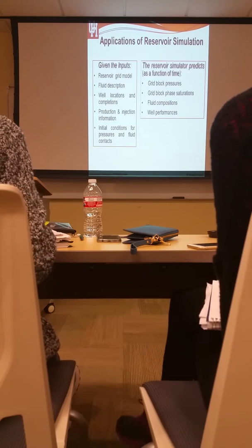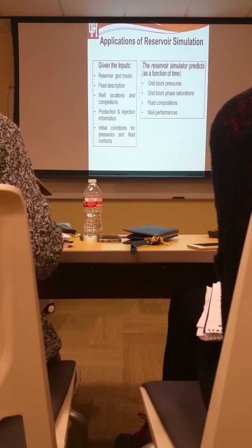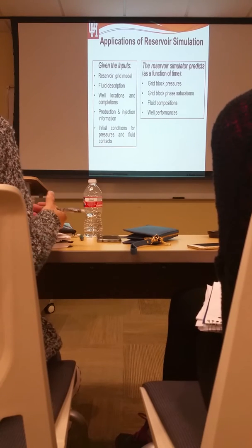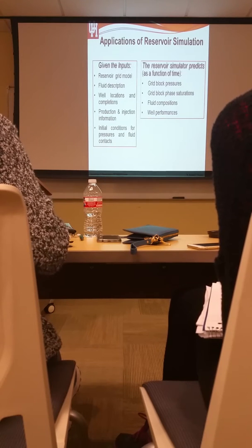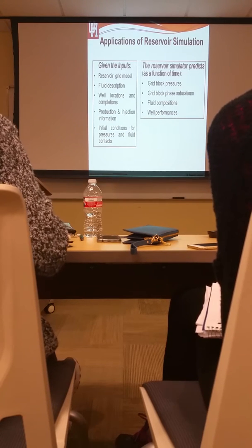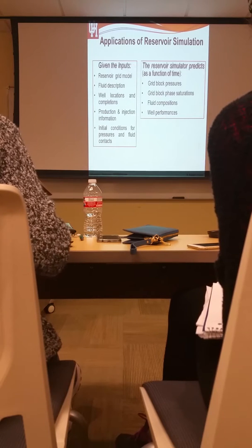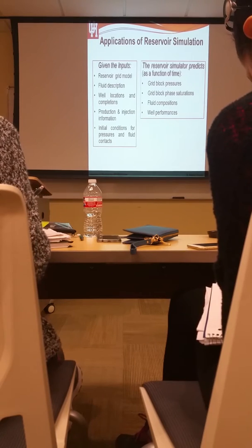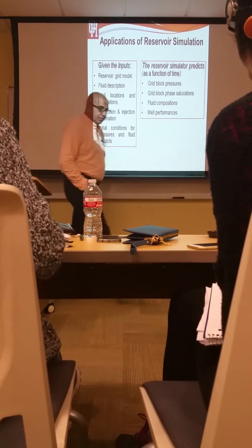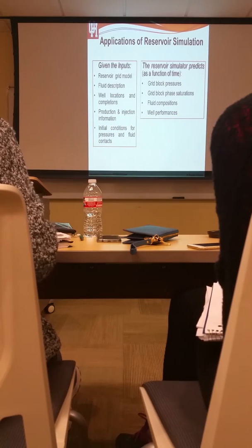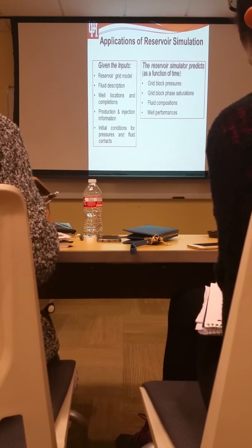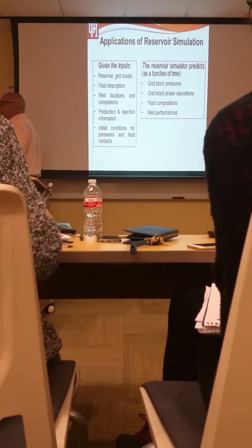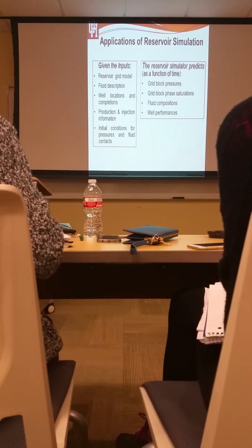Given some inputs: reservoir grid model, fluid description, well locations and completion process, production and injection information if you have it, initial conditions for pressure and fluid saturation. All this information needs to be provided when you deal with reservoir simulation, and more if that's the case. And we talk later about black oil and thermal simulators, etc. But depending on the process that you want to model, you will need more or less, or more specific kinds of information.